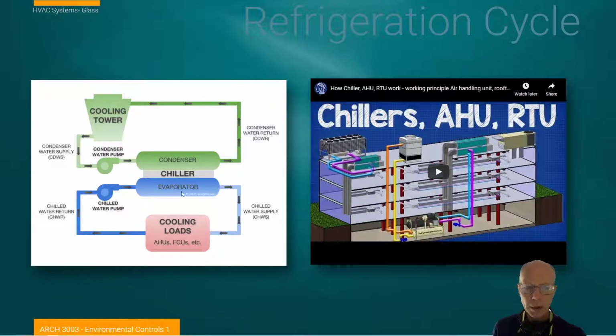They're working on the same idea of a condenser and an evaporator to transfer heat, except that the evaporator and condenser are now next to each other. And the way we're transferring the heat is by moving it through fluids, liquids. So we chill water to cool buildings in the interior, and we reject that water heat in cooling towers, where we actually have towers that evaporate off moisture.